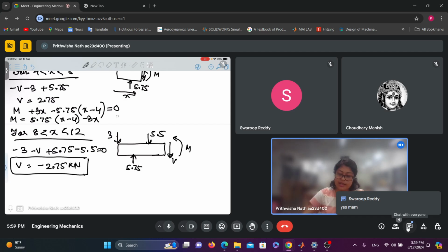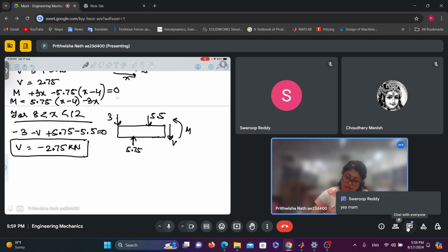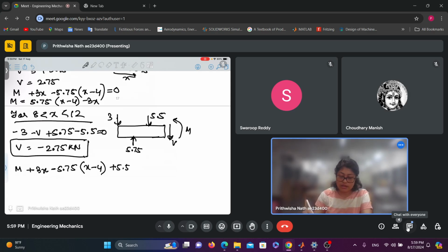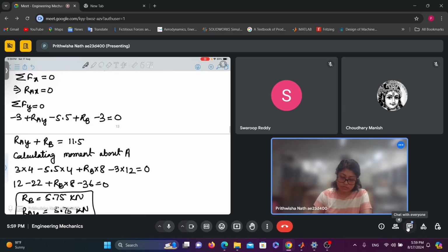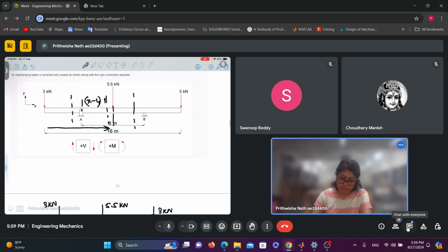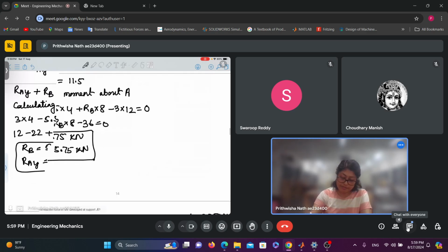Okay. Now similarly for moment, m plus 3x minus 5.75 (x minus 4) plus 5.5, this should be (x minus 8), right?